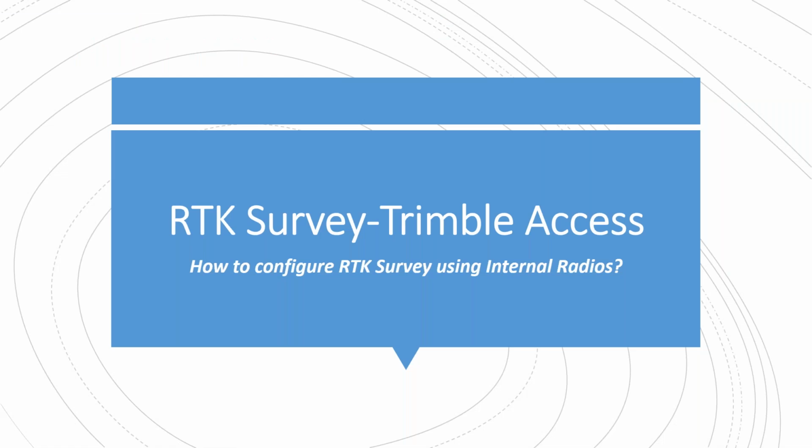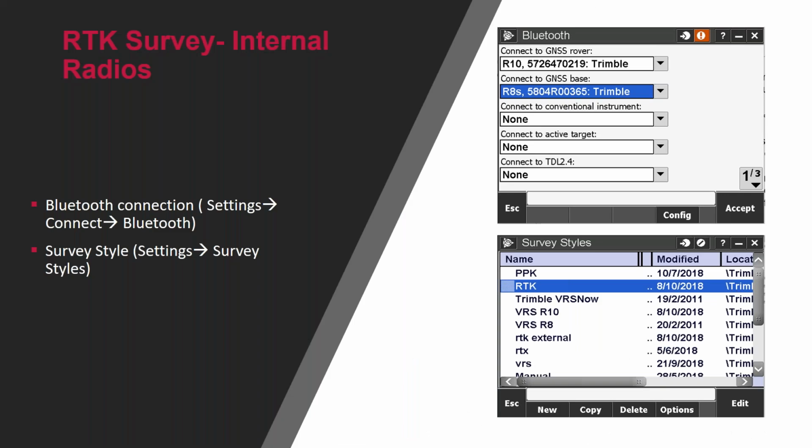So first I will start with the RTK survey within Trimble Access, how you can configure an RTK survey style using internal radios. Let's start with the Trimble Access homepage. The first thing that you will need to do is make sure that you've got Bluetooth connections established between your rover and base. You can see my laser pointer on the right hand side on the Bluetooth settings.